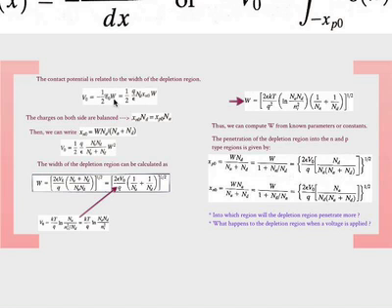First of all, the things that we cannot measure easily are, for instance, the width of the depletion region and the electric field. And you can relate those to the other constants here. At the end of the day, the width of the depletion region can be related to the donor-acceptor concentration. So we know that the side that's more heavily doped will have a thinner depletion region, right? Because you need the higher concentration of charges, which means you need a shorter distance. The more lightly doped material will have a thicker depletion region. So the charges have to be matched. So the logic is important because you can look up the equations.